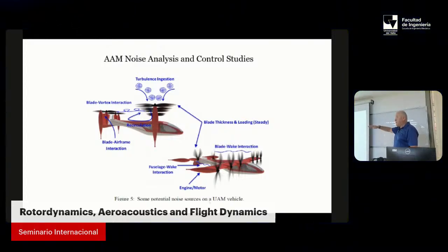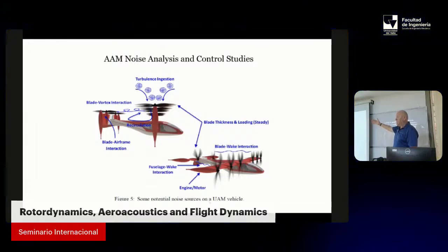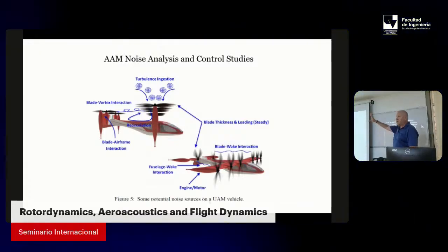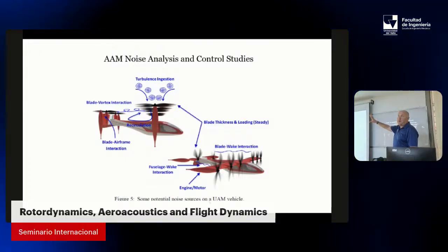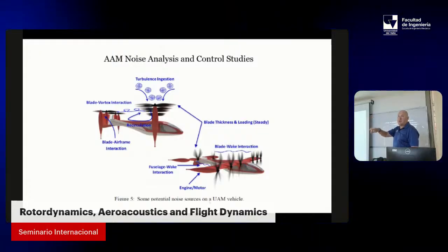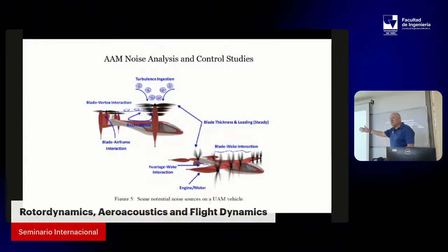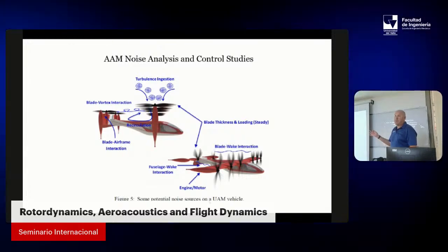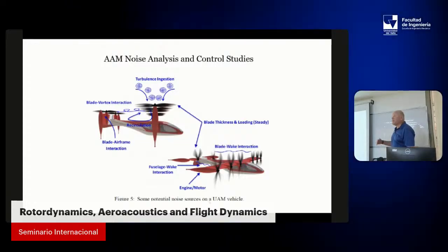When it propagates far away from this unsteady pressure on the surface, it goes into acoustics, and it's called the far field. So there are methods to predict first the near field, then propagate this information to the far field, using methods like Green's function, or the Green's function methods put together into the classical Ffowcs Williams-Hawkings formulation, which follows Lighthill's acoustic analogy. So there's a lot of words there, but it's all the science of acoustics. There's a lot of legacy from the 50s, when Sir James Lighthill studied this.